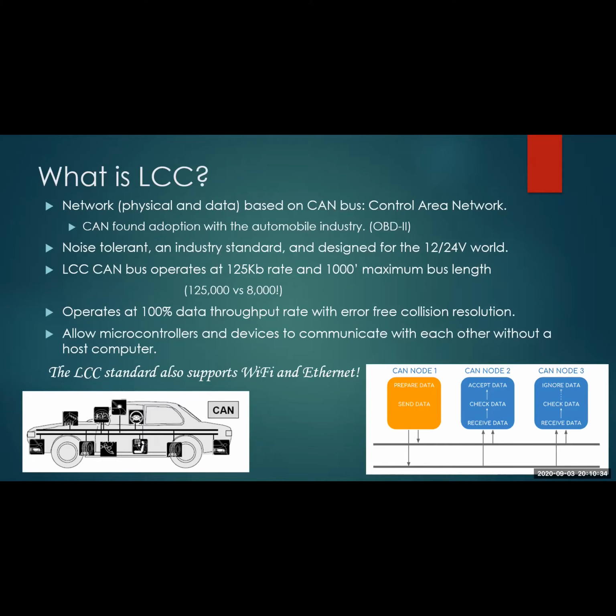It does. And so if you've heard of OBD2, like the interface that you have, that is actually CAN bus that you're plugging into on your automobile. And the idea is the same. It's a noise tolerant system that allows data to be communicated reliably. LCC bus operates at 125 kilobits per second and 1,000-foot maximum bus length. Again, this fits in really nicely. I don't know many layouts. I don't know anybody on the call here have more than 1,000-foot length on any layout run. Would be nice, wouldn't it? But that's going to cover pretty much anything that we need.